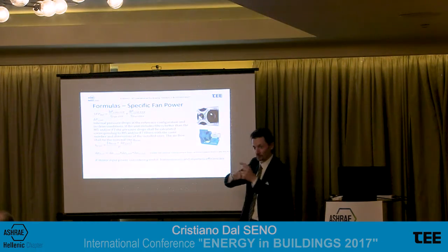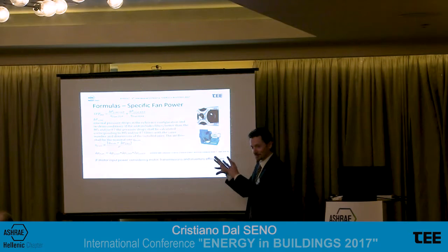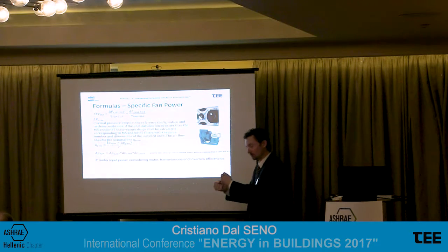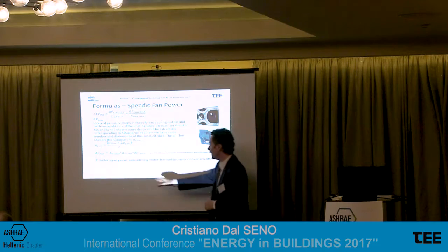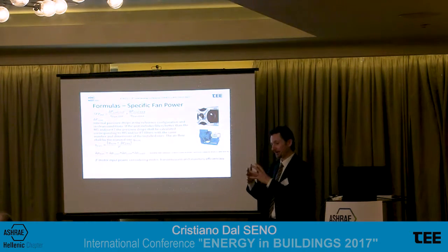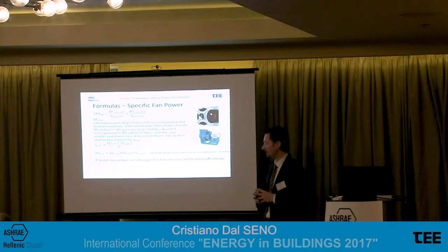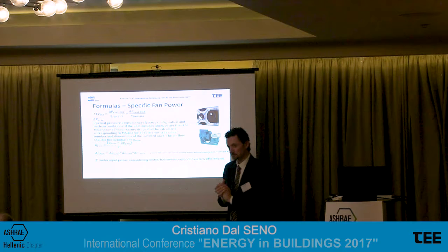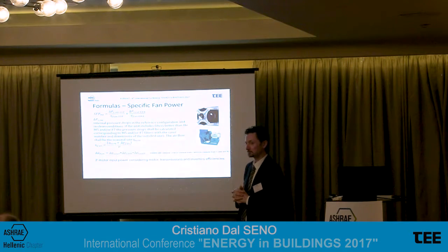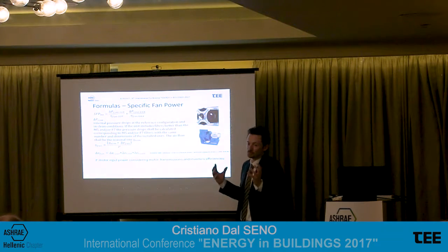So replying to your question, again, we have the indication from the norm that we should also consider the contribution from the ducts, and the internal pressure drops caused by all the components used inside the unit. And when you show the results, you also show the considerations that you took into account when you made the calculations. I mean, the pressure drop at the ducts is something that depends on the design of the system. Yeah. That you don't know. We don't know. We have to take it for granted.